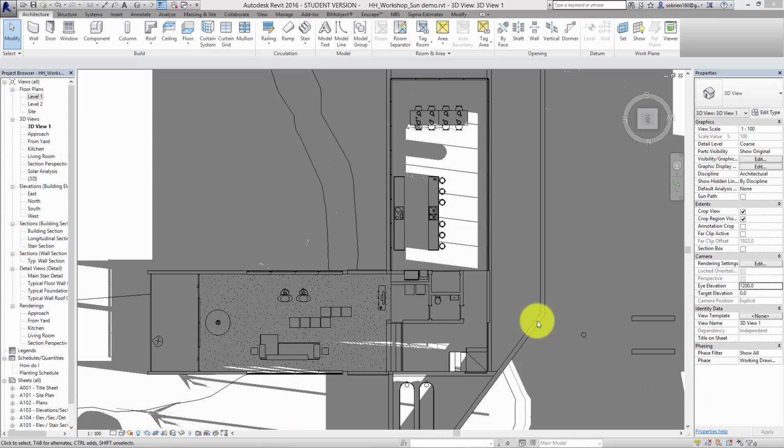Okay, there's one thing that we can also do with this. Before we leave this shadow diagram stuff behind, we can also use it to get Revit to calculate the illuminance of the room, as in how much incident light is falling within the room. And that's what the cloud service is for. So if we leave this like this, and this can be more or less useful depending on the type of project it is, but just to show you how it works.